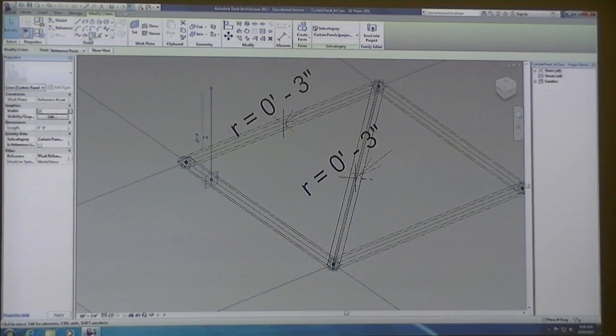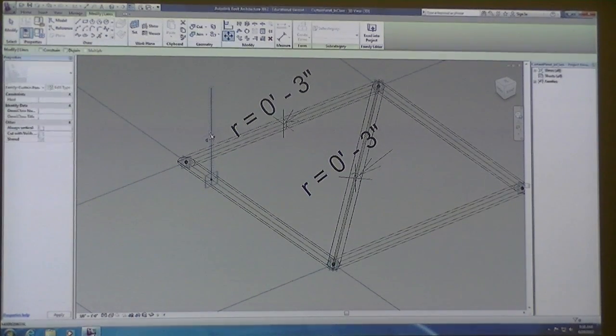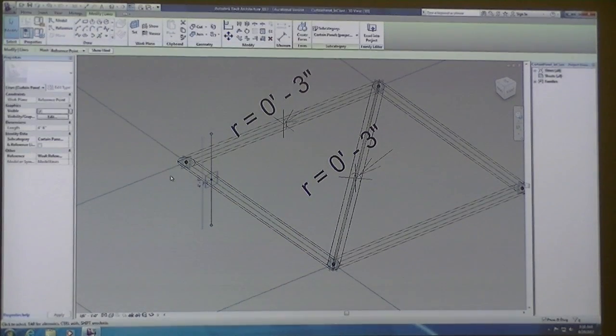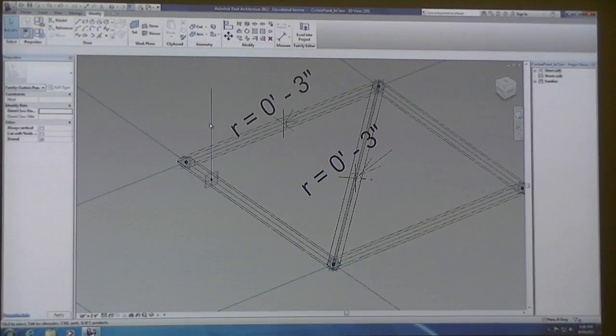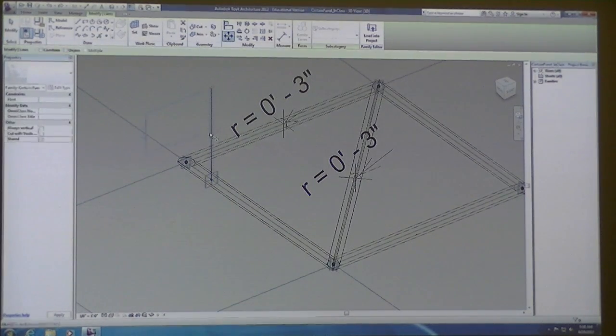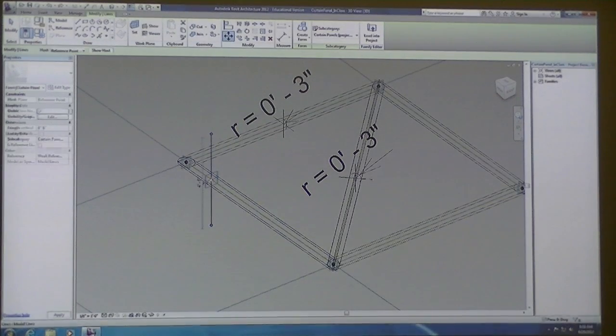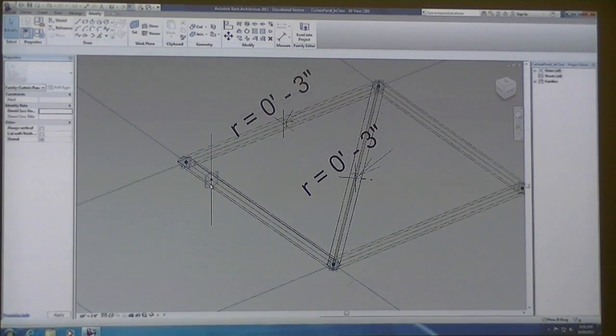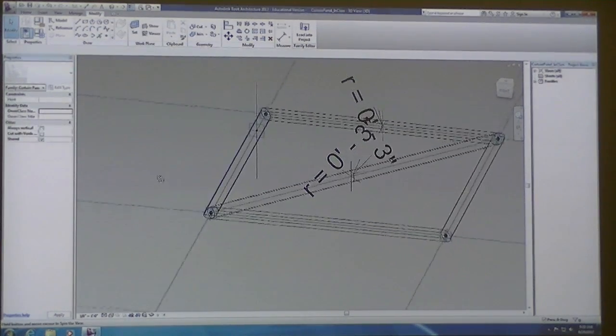Now I've got that line drawn where I drew it straight up, and I'm going to move it so that the center line snaps. I'm going to select that vertical line and click on Modify, Move. I'm going to snap to the center of it. You should get a little midpoint triangle. And then I'm going to move it down to snap to that point. Basically what I need is a line that's going up and down through this point.